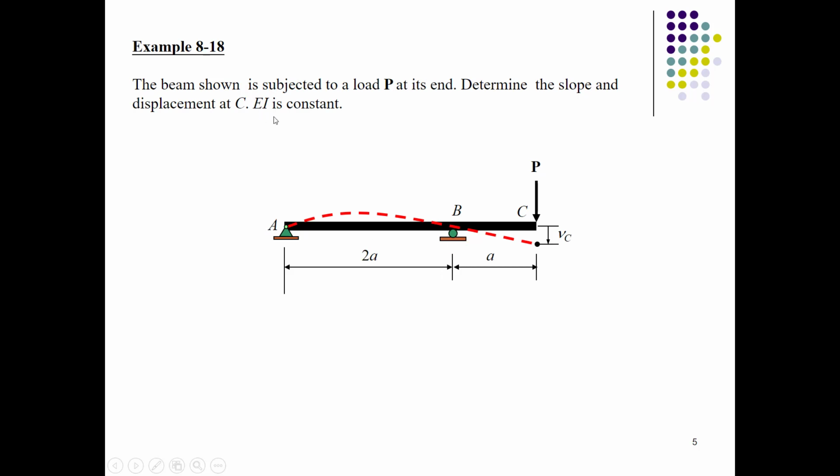Now what we do is we will apply the real load and determine the support reactions, and take the different sections, then find out the moment values by the application of real load, and then apply some virtual load at point C and determine the moment values and deflection values, and then calculate the deflection and rotation respectively.